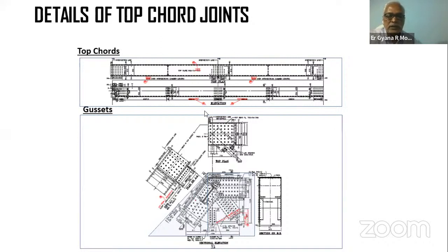So let us say we take one component of the truss. Let us say this is the top chord. If you see at the end here, this is called an end raker. This is the top chord, this is the diagonal, and this is the vertical. There are so many components getting assembled in one place, and all the hole directions are in different directions. And maybe at this particular point, these components are shortened. Then how do you drill the hole accurately? Because the accuracy of our drilling of the hole will allow us to achieve the right camber and the right requirement of this particular girder.